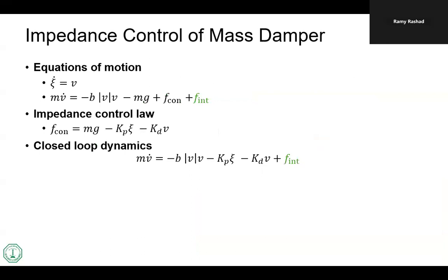And there's something that has the opposite. There's something called admittance control. Admittance control is simply the opposite: instead of force in, velocity out, you have velocity in and force out. In terms of the bond graph, instead of the causality stroke being on this side, it becomes on that side. This is the only difference.